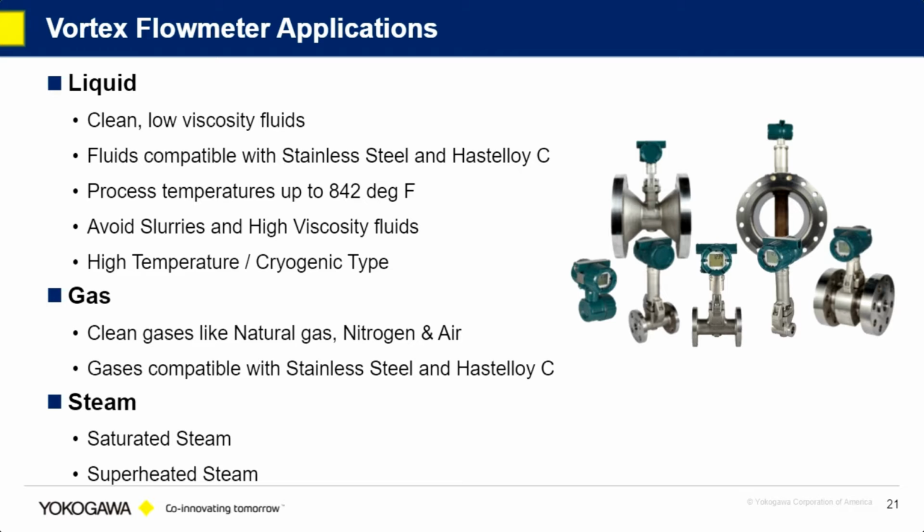or not. Any processes that are compatible with 316 stainless steel or alloy materials, which is a Hastelloy C equivalent. We have high temperature up to 842 Fahrenheit. We can also do cryogenic fluids. Gas and steam, again, no problem as long as it's compatible with the materials.